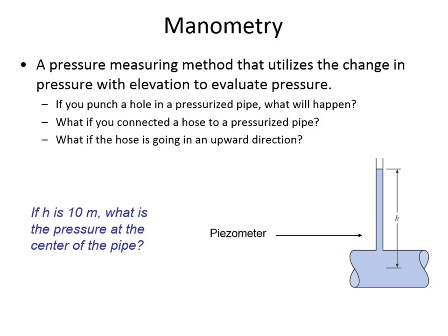Robbie, right? So what's the pressure if the head is 10 meters? Anybody get that? 98 kilopascals. Right, good. Exactly.